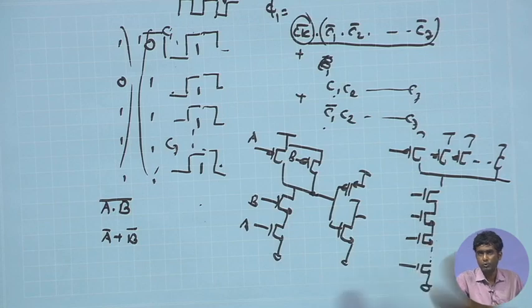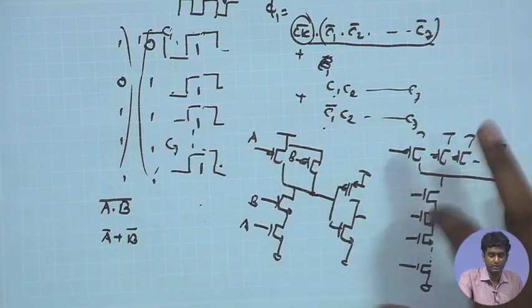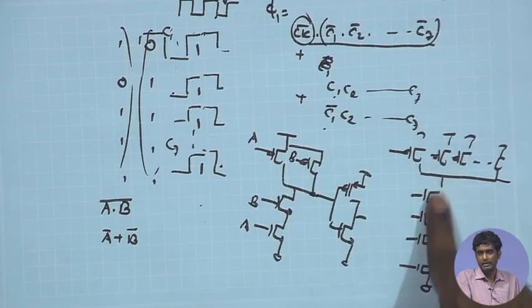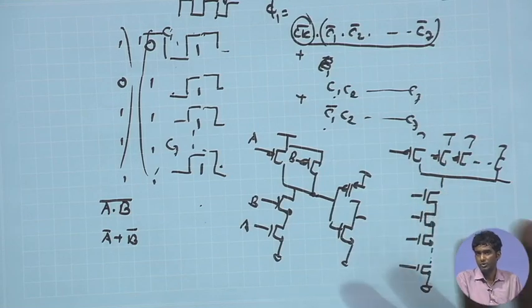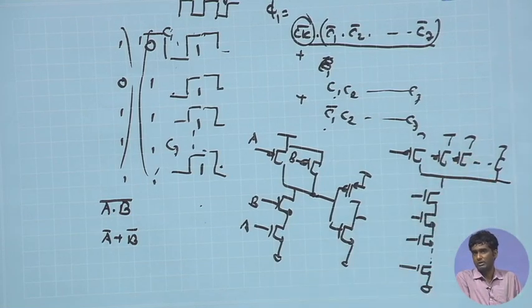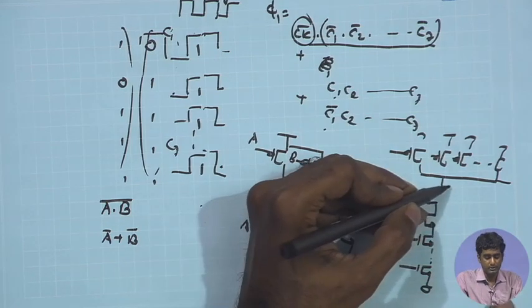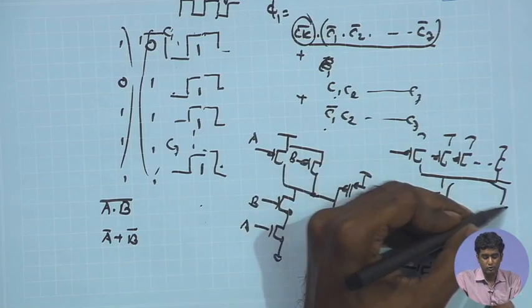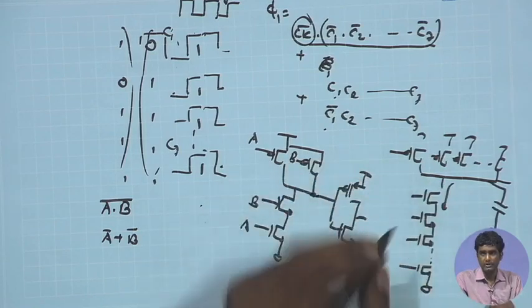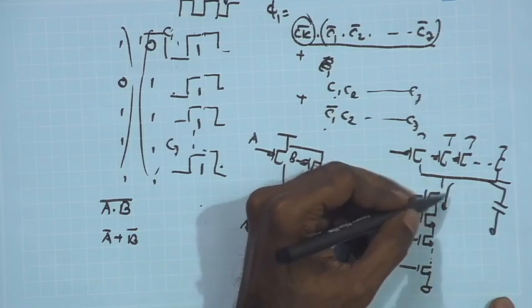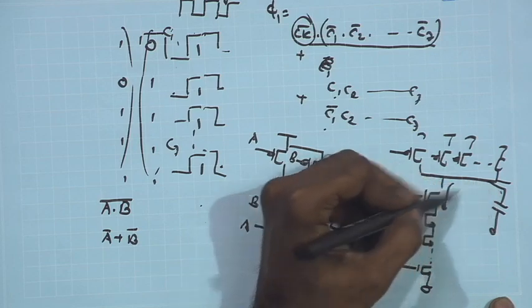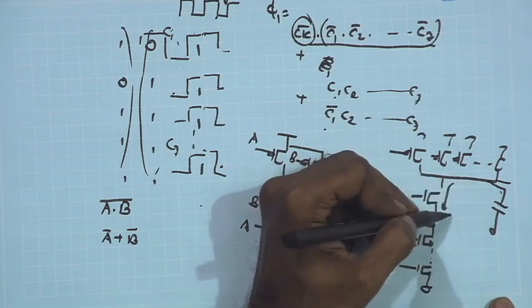And then ideally, of course, I can do this, and in digital circuits we know that we do not need to worry about the voltage headroom just like we do in analog circuitry. These are just triode region switches, and ultimately the voltage drop across them can reach 0. So, I do not worry so much about the voltage headroom across the switches in digital operation, but what I do need to worry about is the transition delay. If you are stacking too many transistors in this fashion, each of them adds to the overall transition delay of the discharge path, and that increases as n square.